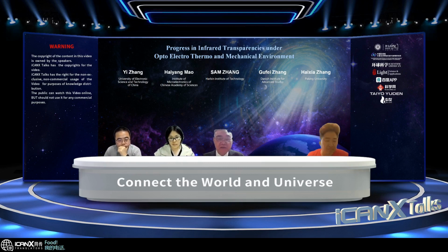For mechanical properties, we usually talk about applications in the long wavelength area, which is 8 to 12 microns or even beyond. For those applications, the mechanical behavior is much more necessary. That is because right now the substrate of this IR window is zinc sulfide. Zinc sulfide itself has a rather low hardness, around 4 gigapascal. Therefore, we need to mechanically protect it.